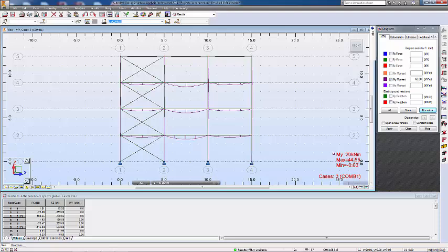So from a structural point of view, this structure is more efficient to withstand the lateral loading compared to the one we had before. However, you do need to put in a diagonal in here to form a stable structure. So this is what we have for the second example, and I hope you enjoy that. Thank you so much. Bye bye.